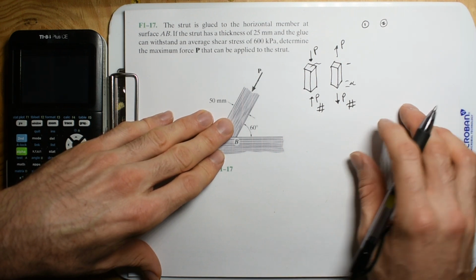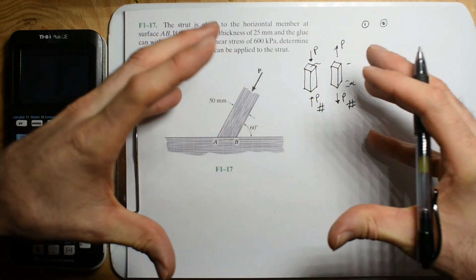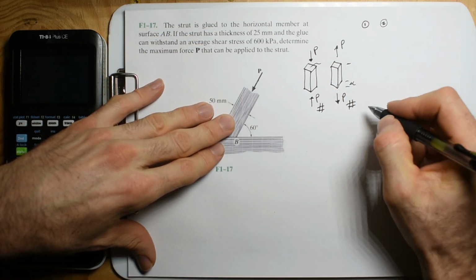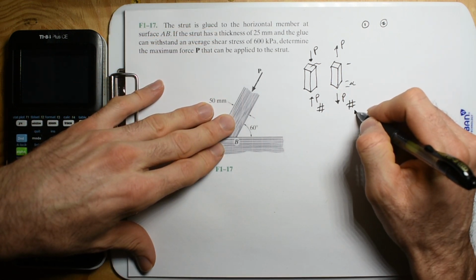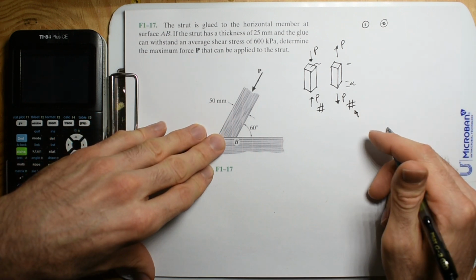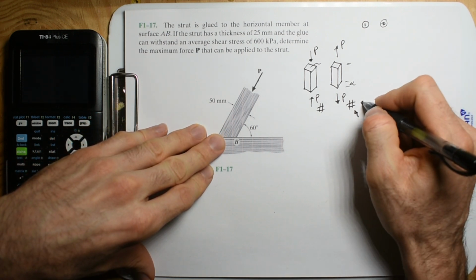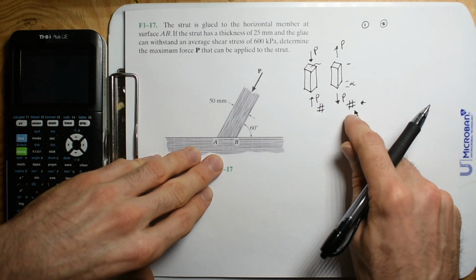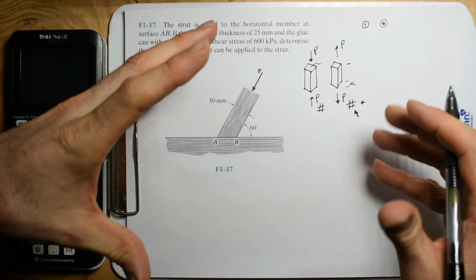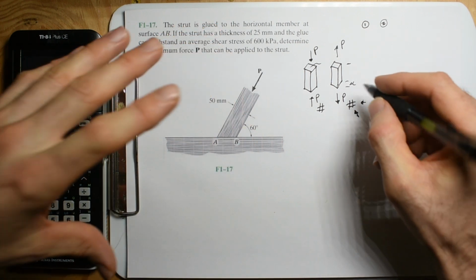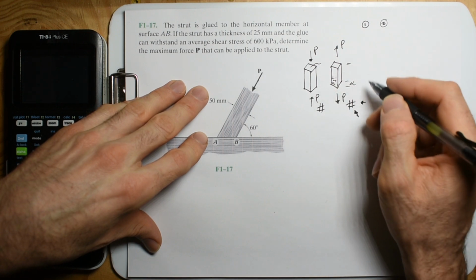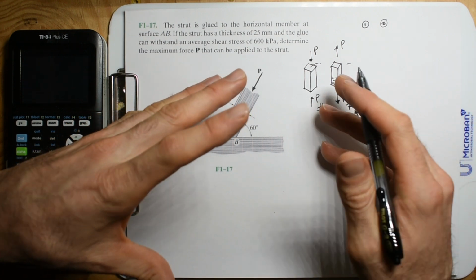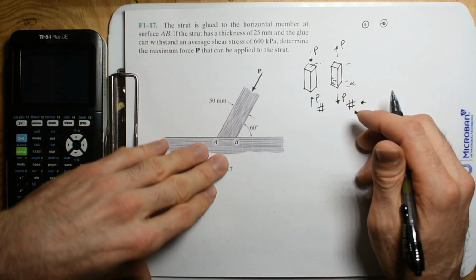permanently. No, it's like the second something actually stretches, turns into plastic, deforms, bends, that's when you went over the actual capacity for that material. And that capacity is a high enough number that most every structure that gets built is at a lower number than that. And if you are under this max load, what happens is that every molecule returns to its original length, shape, volume. So if I put a load on it, it stretches, but if I let go of that load, the material gets back to its original state.